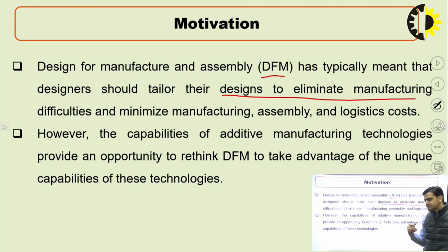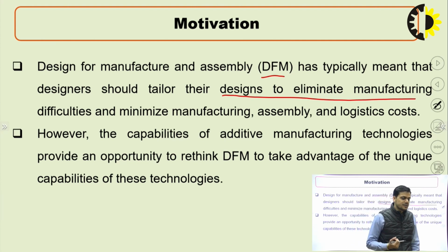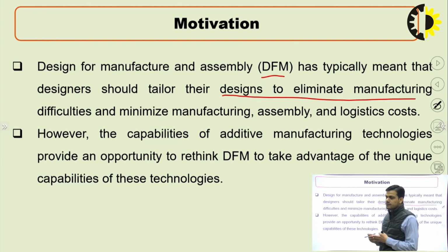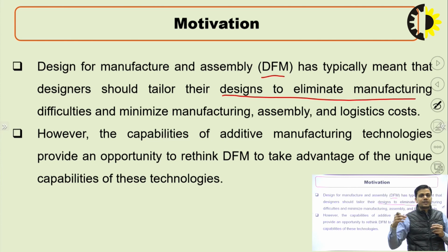As for the purpose of using additive manufacturing, you can change your design. If you find that the end product is not suitable for you, you will have to change your design. In the conventional process, you have to change the whole setup for that particular end use product. But in additive manufacturing, you only have to change the design, which is basically the CAD model, and that CAD model is converted into the STL and finally into the final product.